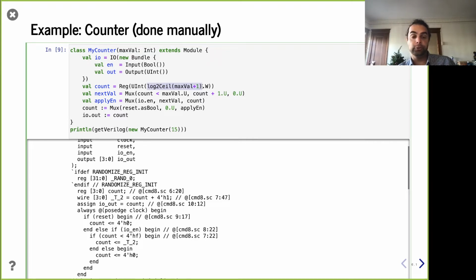So this is log2 ceil, or ceiling, right? So remember, in your rounding modes, normally you can go round down or round up. Log2 ceil, we're going to compute the base 2 logarithm and take the ceiling. This is a very common operation you want to use when you want to figure out a bit width, right? If I have something, I want to know how many bits it needs to hold it, I need to not only know the log base 2, but the ceiling.